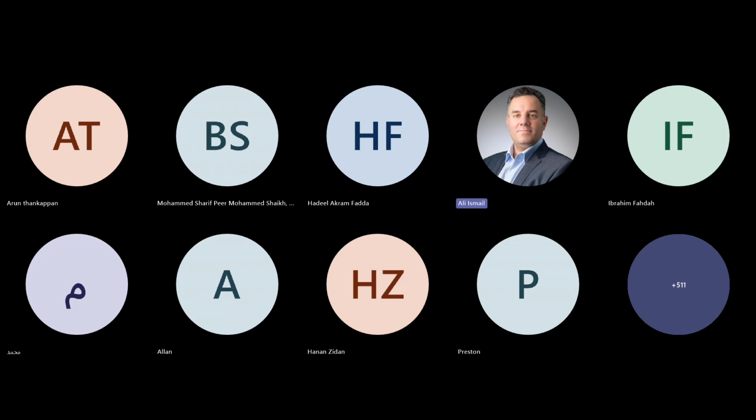But in most cases, I think it is a wise idea to check and analyze the IFC model before submitting to the Build in Dubai platform using any desktop viewer like BIMcollab Zoom, BIM Vision or Solibri. There are many free tools available which allow you to check whether your model is exported correctly, and give you opportunities to filter and check your models in a good way.